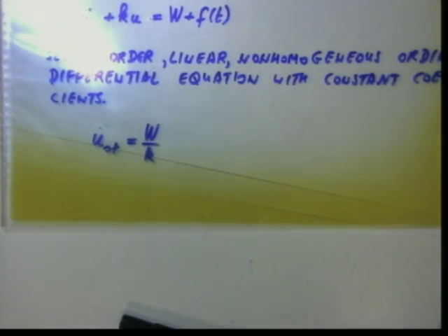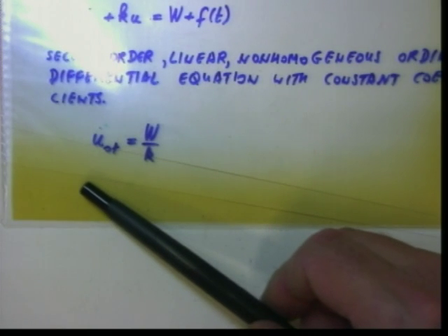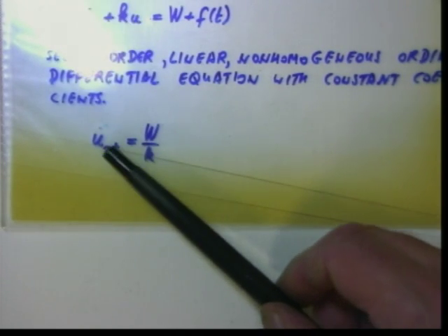So if there is only static constant, no vibrations, just because I put this mass on the spring, this spring should deflect more because I put some weight on it. It had an unstretched length. Then I put a mass. It's a point mass, but it is a mass. Then it would be displaced from that original position. What would be the displacement? It will be weight divided by spring constant. That I call u static. I will call that static displacement, ST.